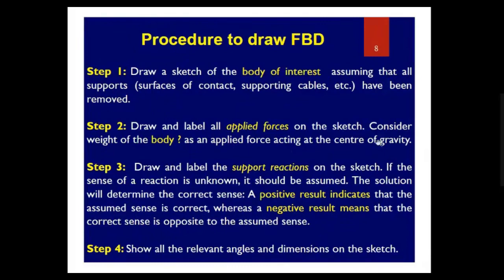If in the question it is said that you should not neglect the weight of the body, then you should consider the weight of the body as a force as well, which should be acting through the center of gravity. So these are the two key steps in drawing the free body diagram. The rest of the two steps concern the analysis of that free body diagram, which we will discuss in the coming lectures.